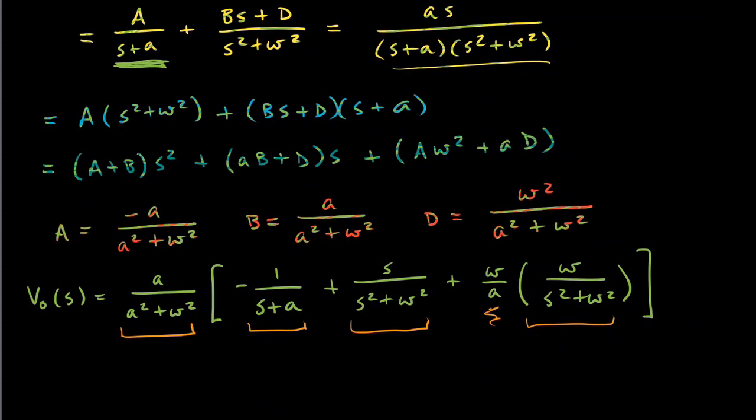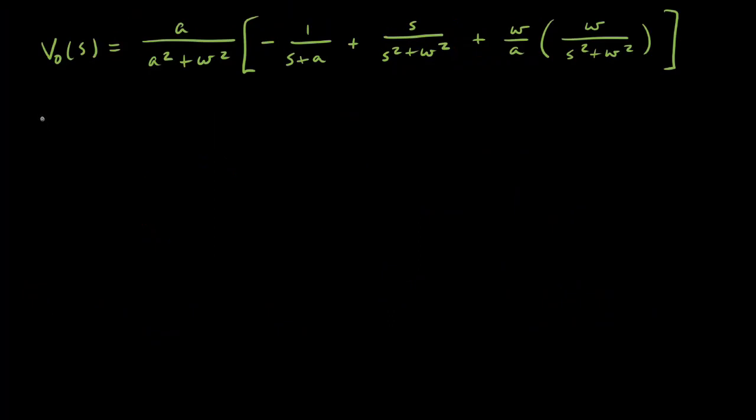All right, so let's go ahead and plug things in and see what we get. Looking at this, V out of t equals, well, I can still leave this term out in front. It might help me to do so. But I am going to convert back and plug in the value of 1 over RC for my A. So that's going to look like 1 over RC divided by the quantity 1 over RC squared plus omega squared.